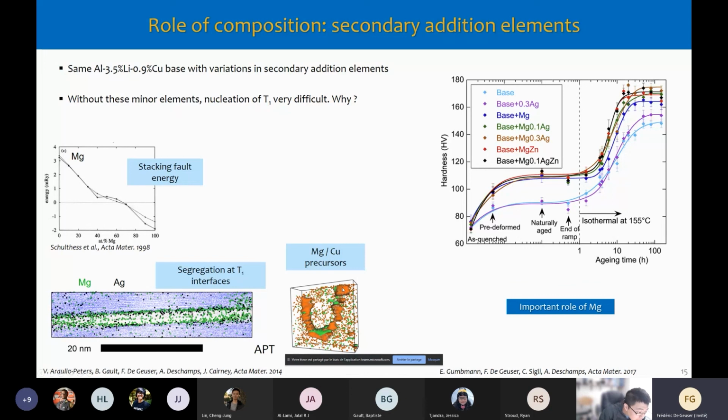Yeah. So there's actually an increase of magnesium and copper at the dislocations. And if you don't put magnesium, you don't have these magnesium at dislocations, obviously, because there's no magnesium. And the result after aging is that what you mostly see are theta prime and not T1s. And these theta primes will actually be mostly associated with the dislocations.